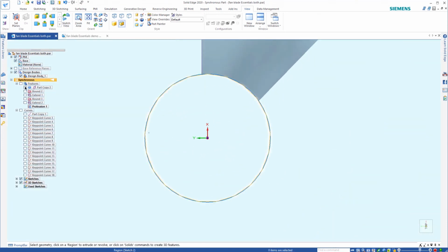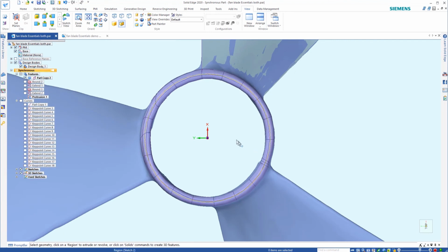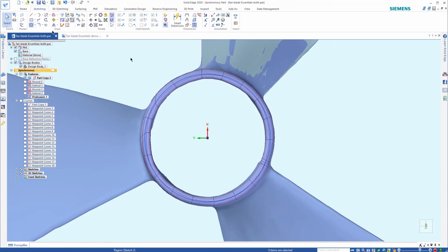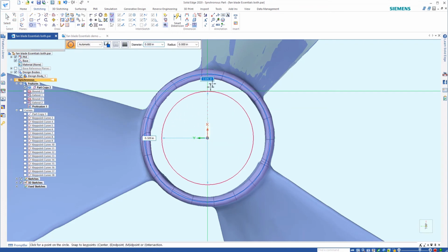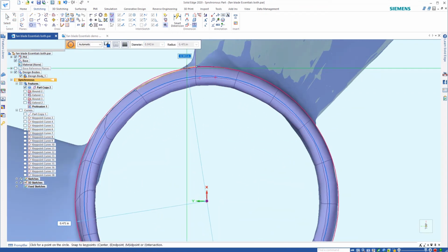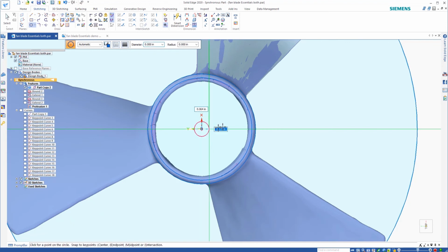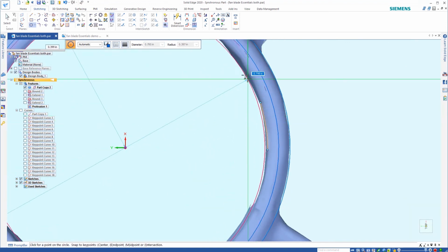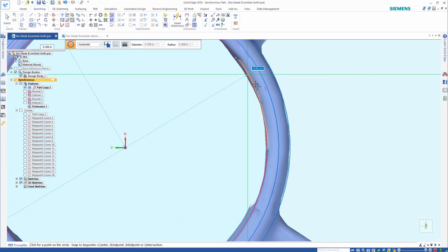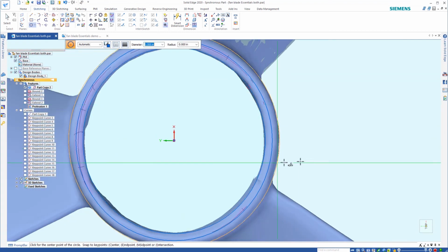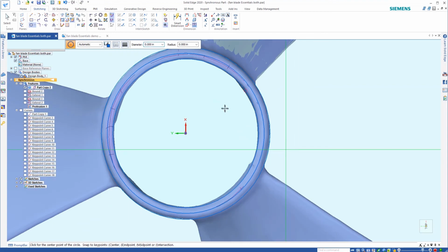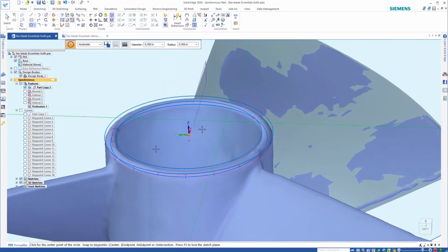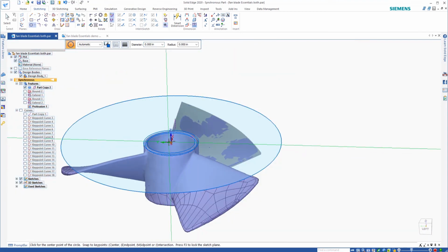And this again is where the auto surface comes in handy. So you can come back over and turn that on. And let's create our inner and outer shape. So if I'll just create that, the outer and inner. And again, you can dimension it as you see fit. But you see that I just drew the two shapes.